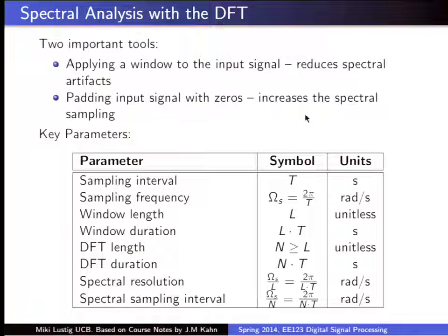But I can then take that and zero pad it. Did I improve my spectral resolution? You'll see that we don't improve our spectral resolution. But we sample the DTFT more finely. So it's just making the DTFT plot nicer, but it doesn't improve the resolution.